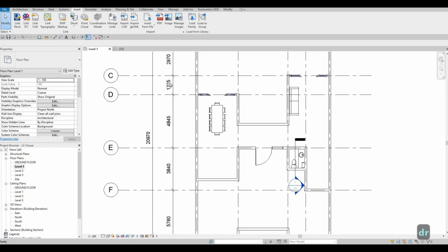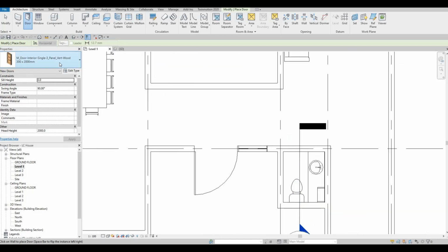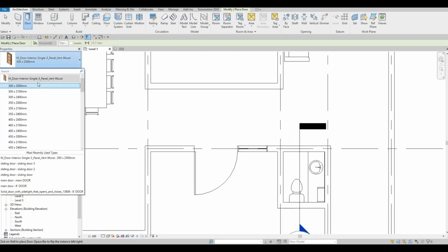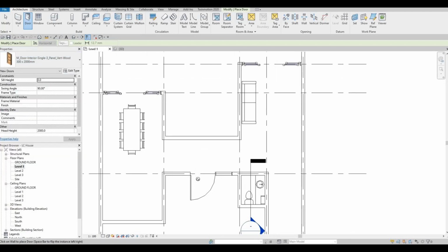You have selecting many families, just say yes, I want to load them all. So now DR, that's the architecture door. And then from here, I know this is very small. We're gonna maintain the 2000 height for all of this. The only 2400 height is this one, and around 24 here. But we might change that so that it looks much better outside.